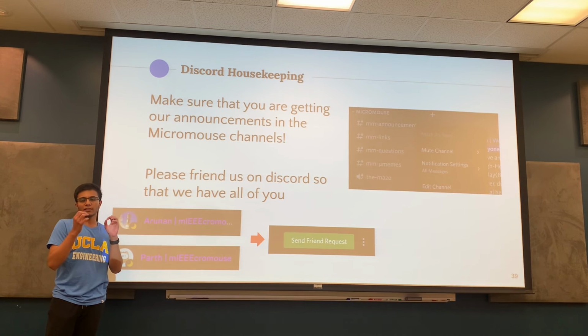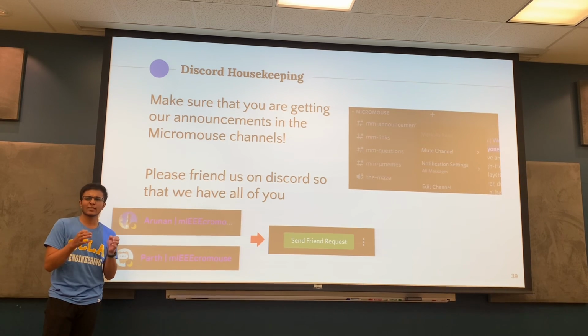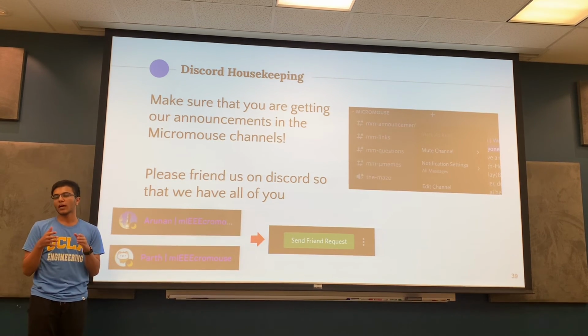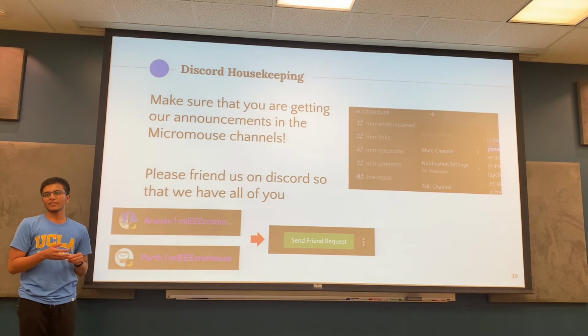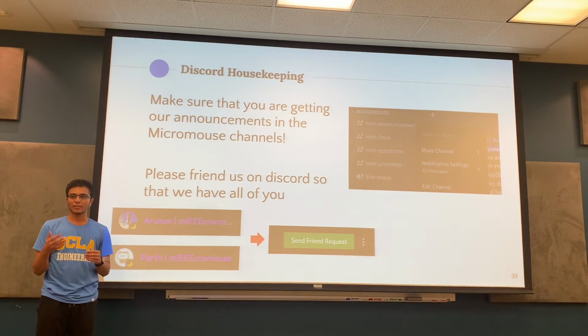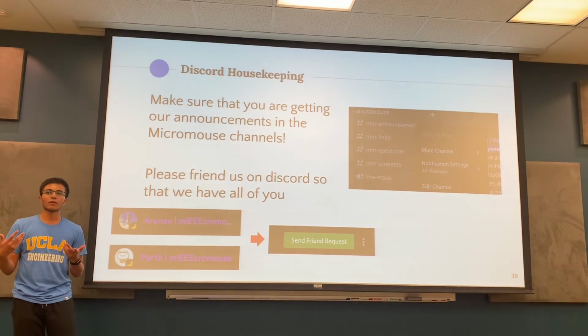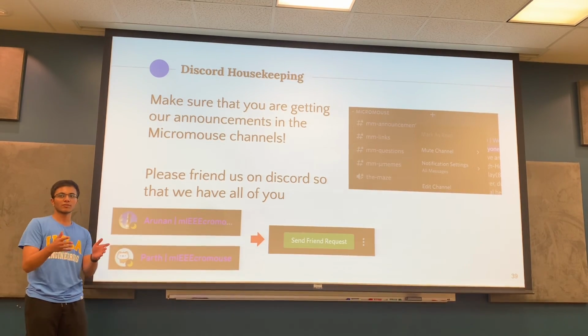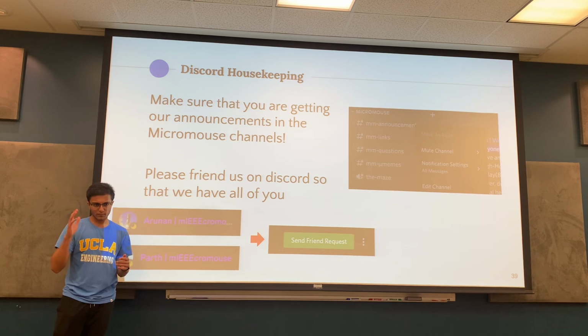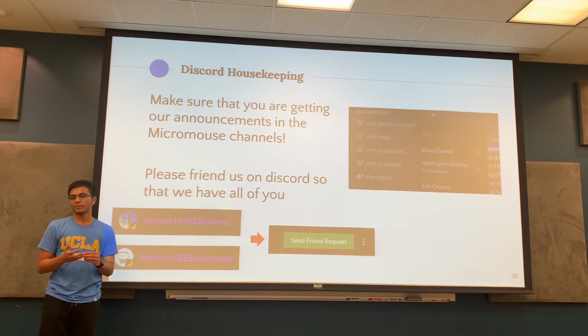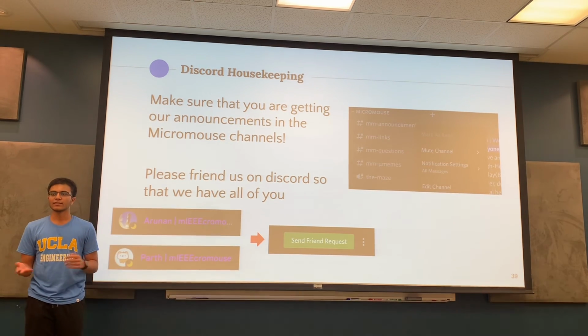And the encoders can tell pretty precisely how many ticks have gone by, and based off of the encoder values, you can tell how much the mouse is moving. Obviously, it will lead to problems if your wheels are skidding, because your encoder counts will go up without the mouse moving. But there are ways to get around that as well, by using acceleration to prevent skid and stuff like that.